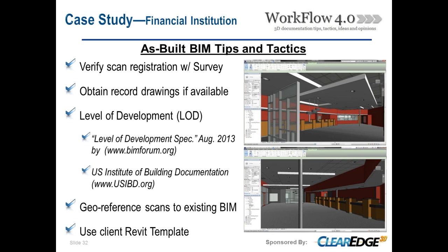For us, we still rely on verifying our scan registrations using survey control. It's not a difficult step, and it gives us confidence that we're providing engineer and design grade point clouds, not only when we model in-house but also when we're just providing point clouds to our clients. We have the confidence knowing that the point cloud is accurate within the tolerances. So we're big believers in using survey control along with our scanning operations.